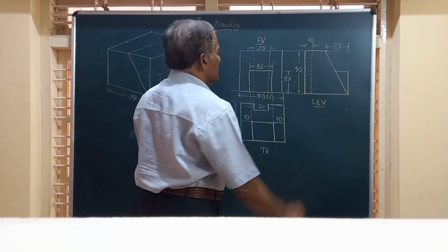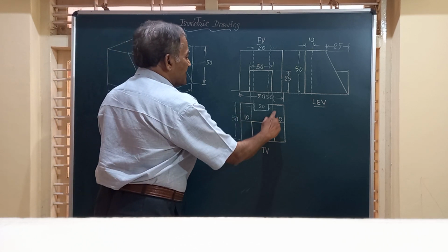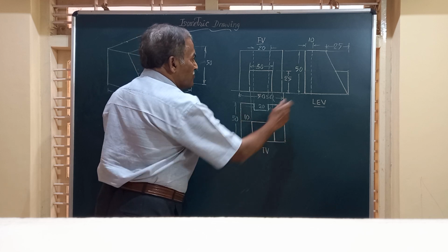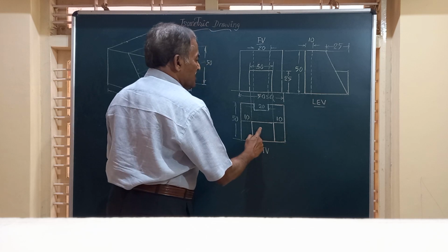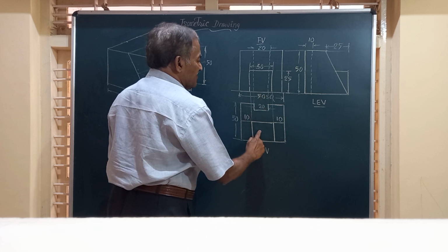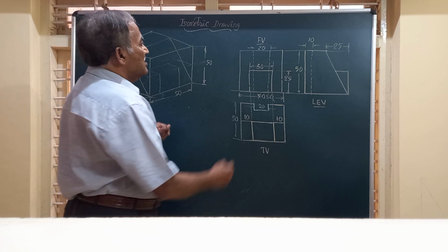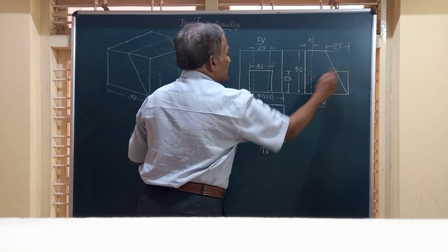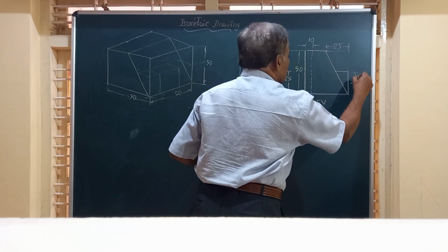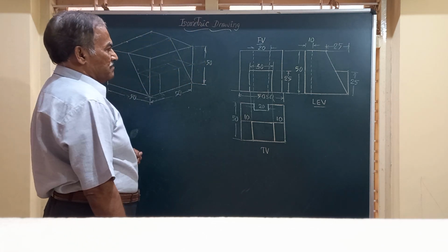I have shown here. So friends, in the top view you have something like a C or U shape solid, and this is the sloping surface corresponding to this. This sloping surface is seen as a rectangular box like thing in the front view. And friends, let us see how to go ahead with this. This height of this is 25, that you can see here, friends. That is attached to the sloping surface is this triangular surface which has got a height of 25 mm.